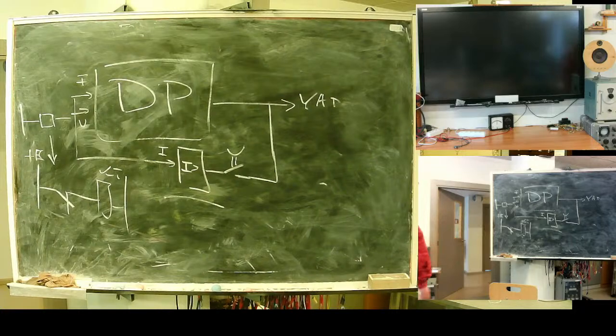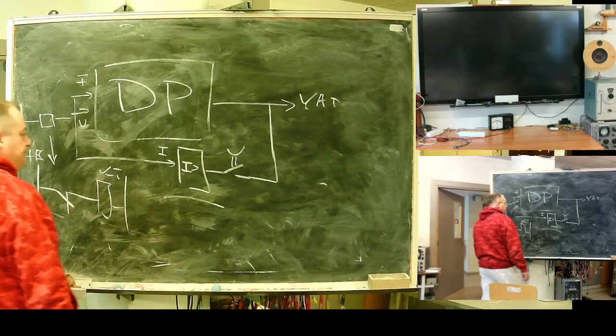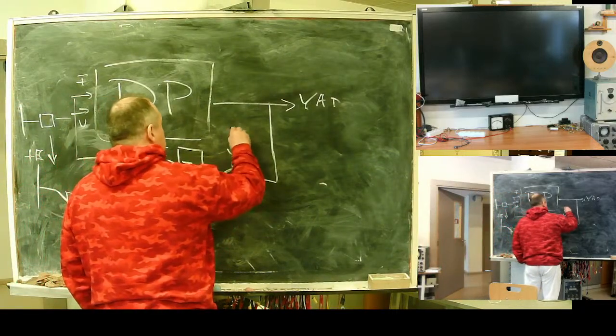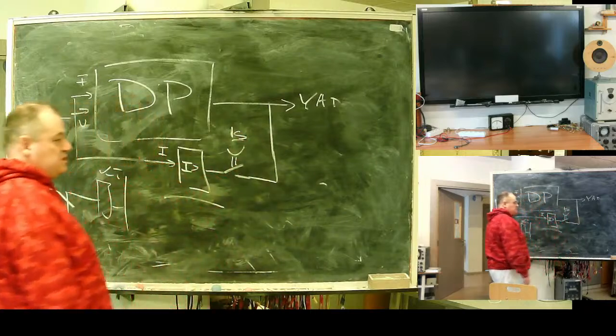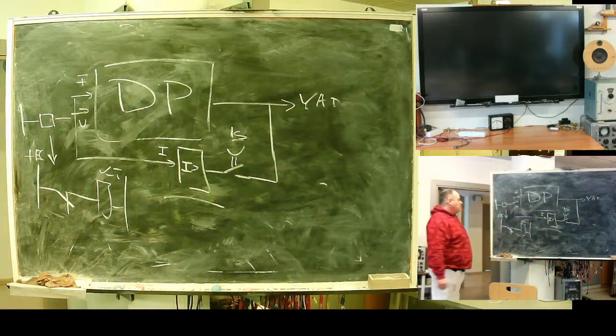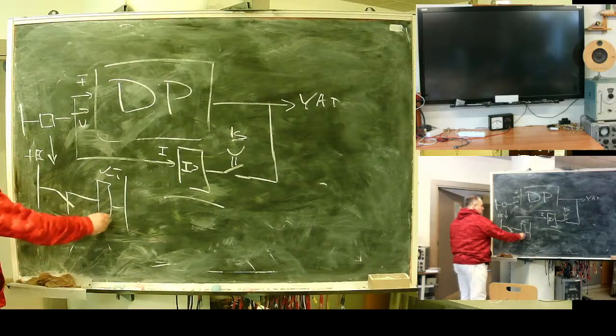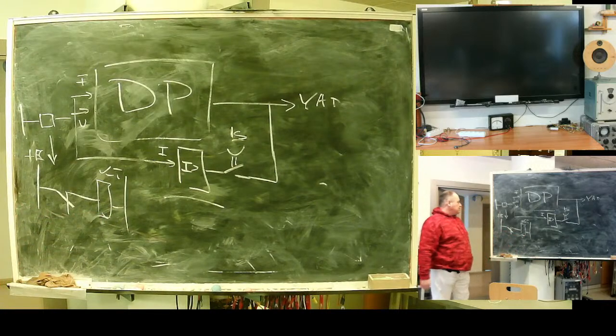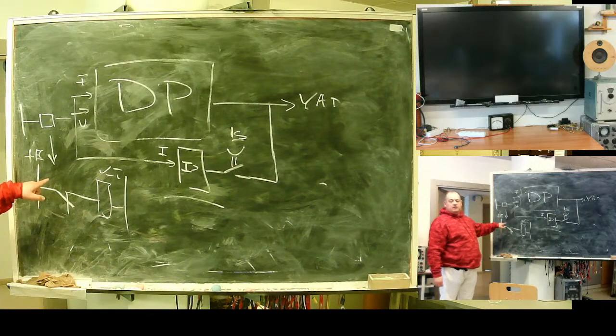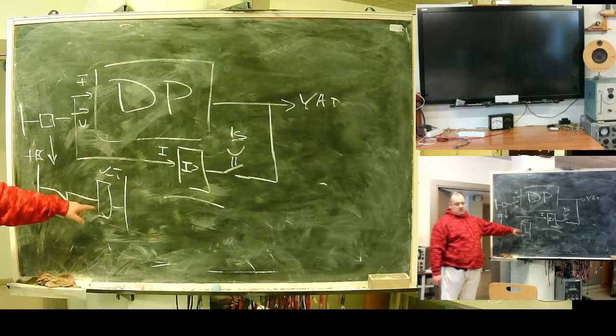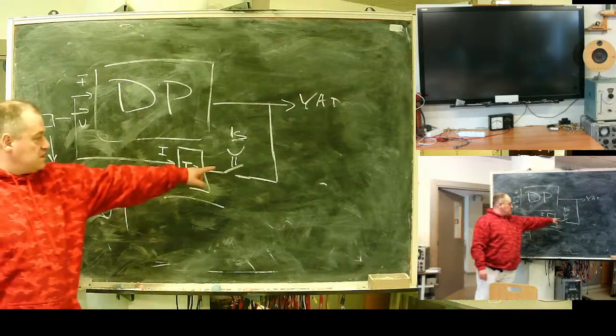Active for time max 1 second. Maximum it should be active for 1 second from the moment. How will this work? When switch is off, time relay is energized. These contacts are closed.